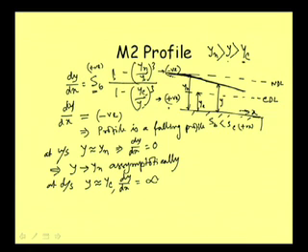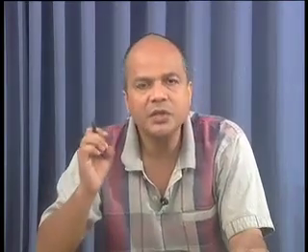So at the downstream point, when y is almost equal to yc, dy/dx is infinity. By that, what do we mean? dy/dx is nothing but the change in y due to a small change in x, and it is infinity. It means you change x by a small amount, and your change in y is very large.